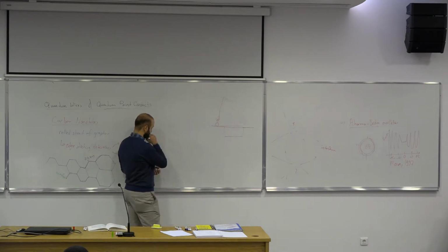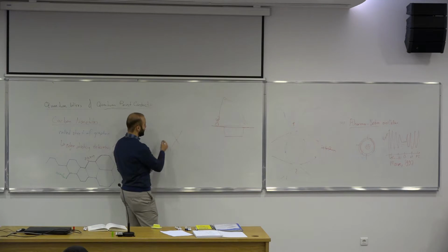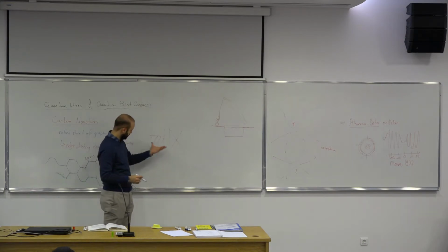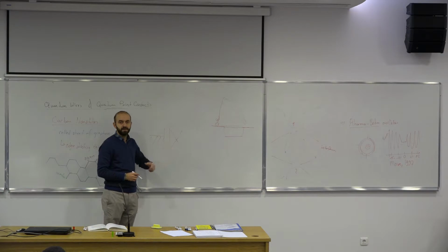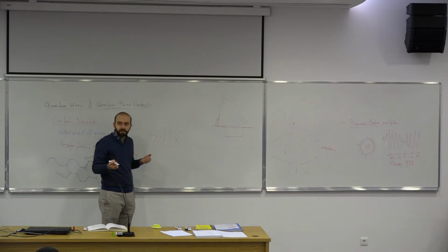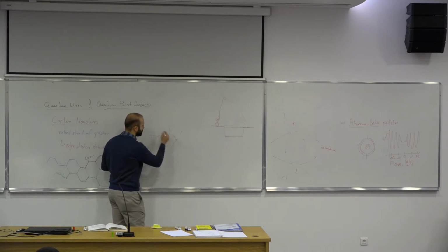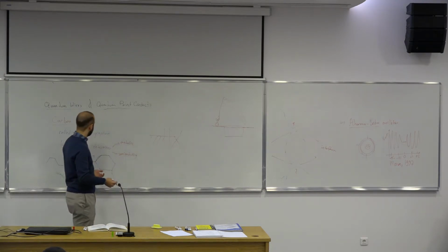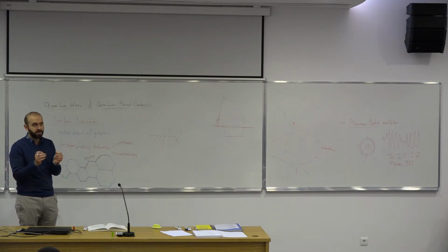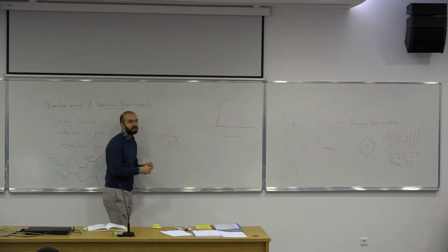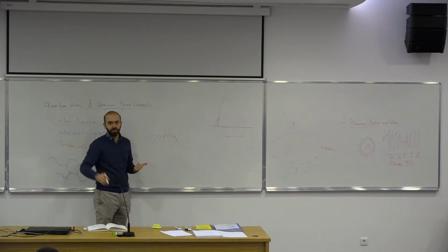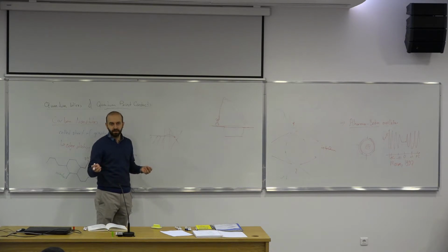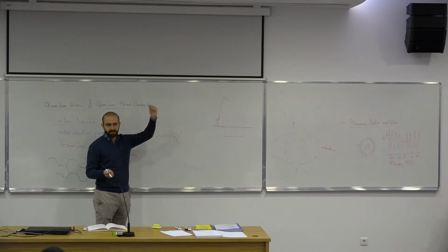What you get is you have the carbon nanotube, and then you have a tunnel barrier, and then your metal. So whenever you put contacts on a carbon nanotube, there's always a tunnel barrier that somehow you cannot get rid of. So any electron that you try to send from metal to the carbon nanotube has to go through this tunneling barrier, which basically ruins that quantum point contact nature. So as soon as electrons tunnel, now they're in the quantum wire, but as for the measurements, it behaves as a classical conductor. So you don't observe any of the conductance steps that we measure.